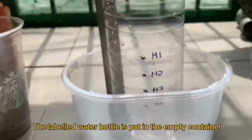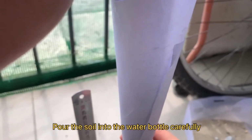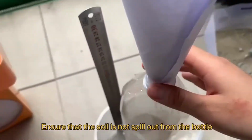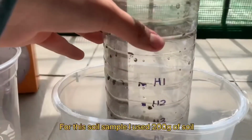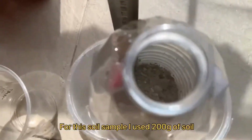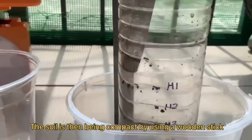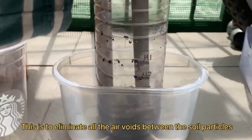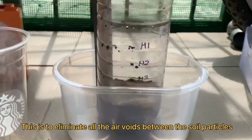The labeled water bottle is put in the empty container. Pour the soil into the water bottle carefully. Ensure that the soil is not spilled out from the bottle. For this soil sample, I used 200 grams of soil. The soil is then compacted by using a wooden stick. This is to eliminate all the air voids between the soil particles.